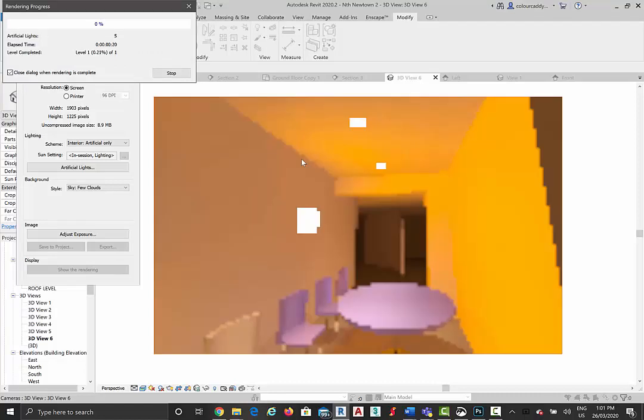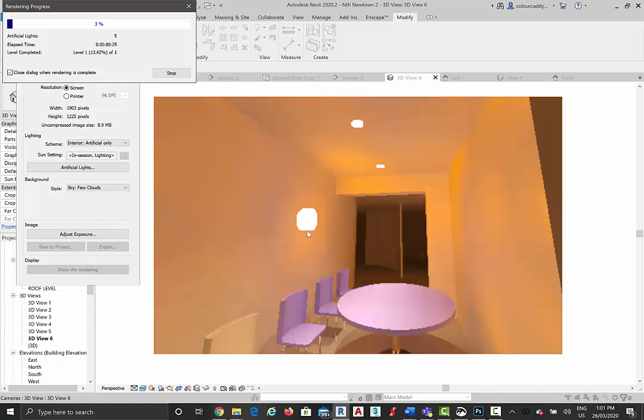Okay, so it still looks very bright, but this is on draft. We should be getting a bit of definition there. Might just have to leave it to finish rendering. It's starting to get a bit of definition, but it maybe even needs to come down further. So you can go easily as low as 10, and you'll still see some effect from the glowing. But notice how over here we're starting to get some unusual artifacts. It's all to do with the way the photons emit from the light source. And again, it's because the material is acting as a light source as well. So we've got to think about that when we adjust these things.